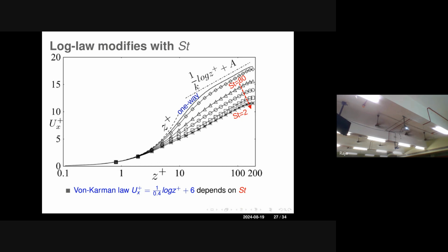But what I can really see is, for typical Lagrangian particle tracking and so on, the typical justification is this: unless your particle size is way smaller than the smallest scale you are resolving, you can't justify it, because any size comparable to that starts shedding wake, or perhaps you need to really resolve the stresses created around the particle.